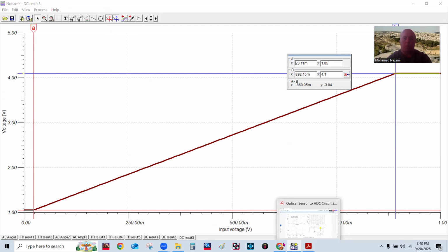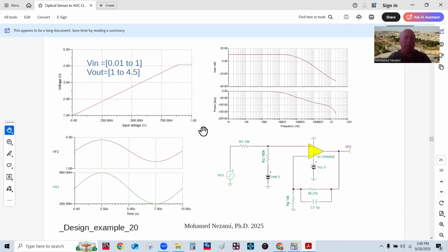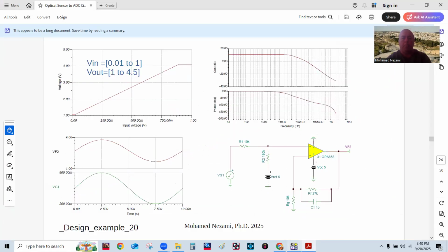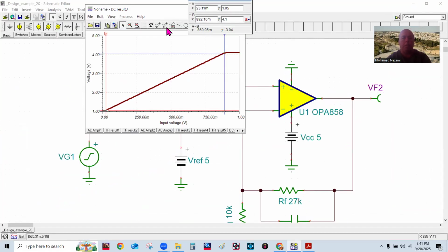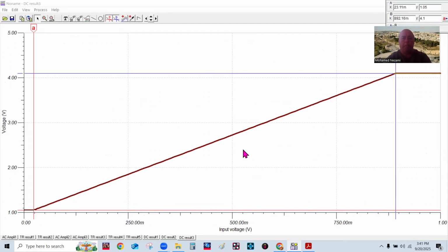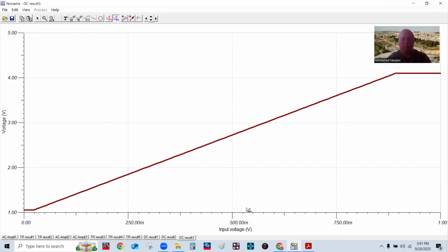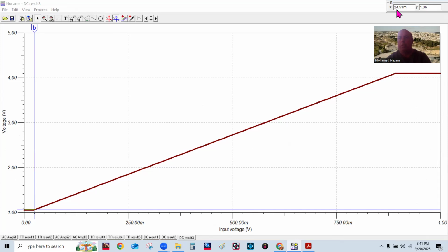It's not reaching out to 4.5 volts quite, and that has to do with the op-amp really. If you really need to solve this, you need to add a little bit more DC on the signal. Now the value of B, you can see very simply by going to the zero value in here, and that's basically 1. In our case, it was 0.96, which is close. You can go down here lower to see it.